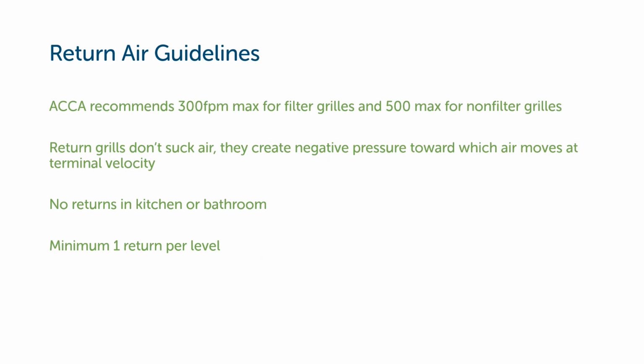And here are some guidelines for return air. Returns do not have much effect on a room's air movement, regardless of the face velocity. They only grab air about a duct diameter away from the face, and most of the room air movement is done by the supply ducts.